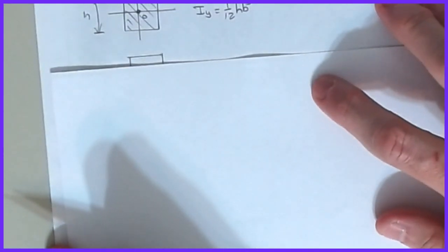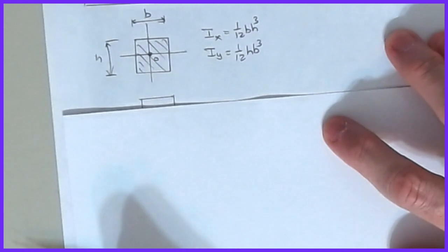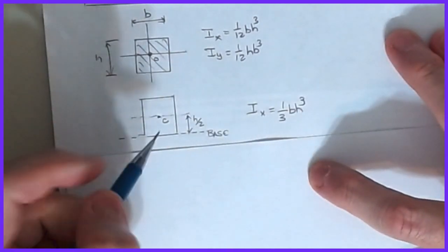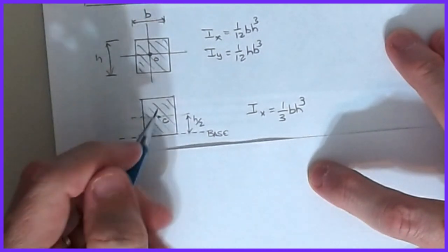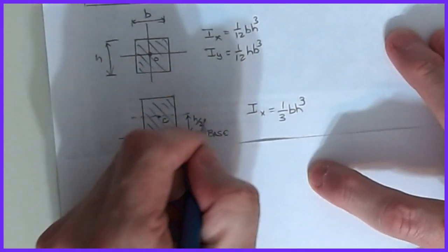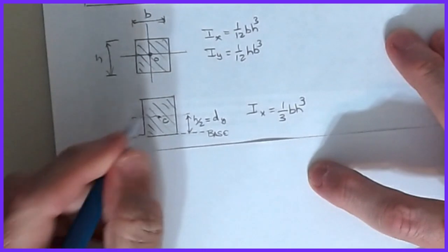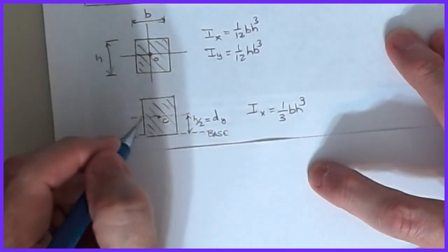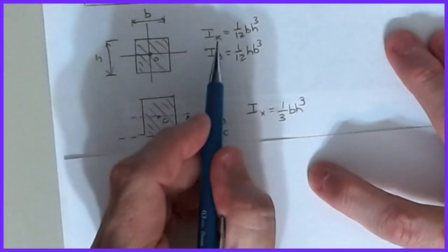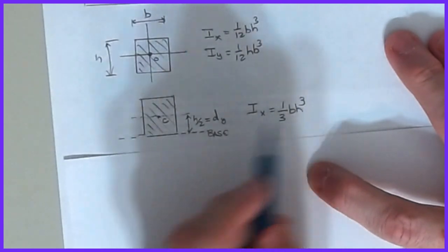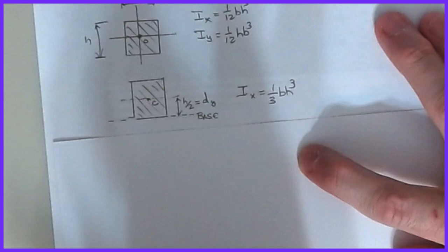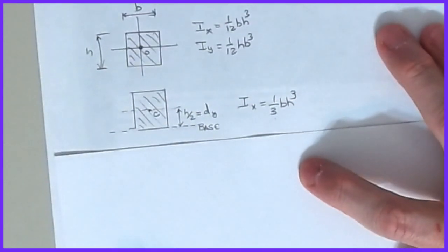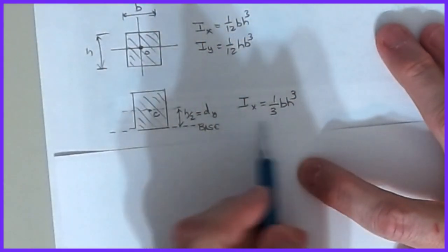All right. Now, there are occasions when doing calculations that it becomes convenient to take my centroid about a different location. And so I'll show you the rectangle that's taken about its base. If you apply the parallel-axis theorem with a dimension of dy here, the A dy squared term changes that 1/12 bh cubed term to 1/3 bh cubed. Like I say, there are reasons to do this. We won't discuss them here, but this is a convenient one to have memorized also.